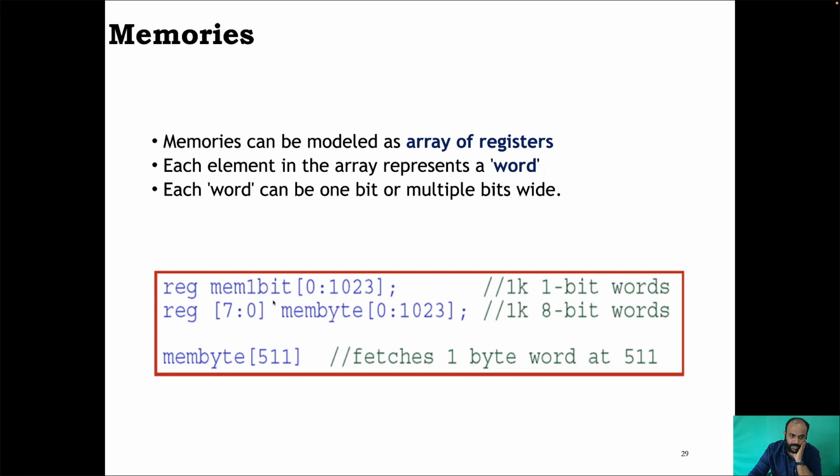In the first declaration, it is written reg mem [0:1023]. So it means you find the bit width specified after the variable name. Here it means the memory is nothing but an array having how many rows? It's an array having 1024 rows, and the first row is the number close to the left side bracket, which is row position 0, and the last row is row number 1023. So altogether 1024 rows are there.